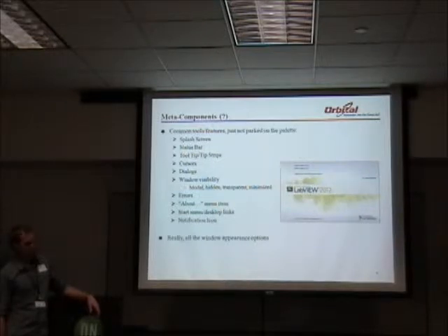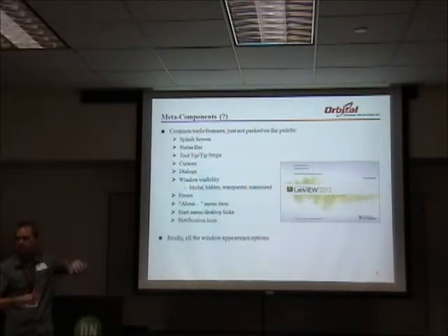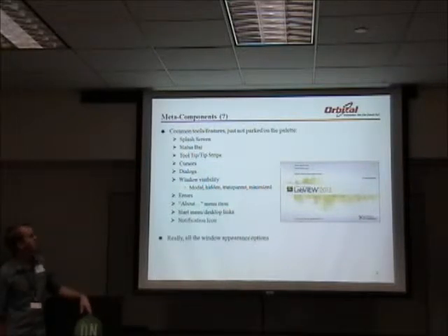Tooltips and tip strips we've talked about a little. If you don't use them, it's where you hover over a control and get kind of that context information. I expect this field to be formatted like so. It's something you don't want to take up space for, but it's nice to have handy. I'll try and dig up on disk where I've got that nice resizable Windows-like dialog that we're going to make a template out of someday. Window visibility is a tool in your quiver. I'll step through the VI properties dialog really quickly. I expect everybody here is familiar with it.